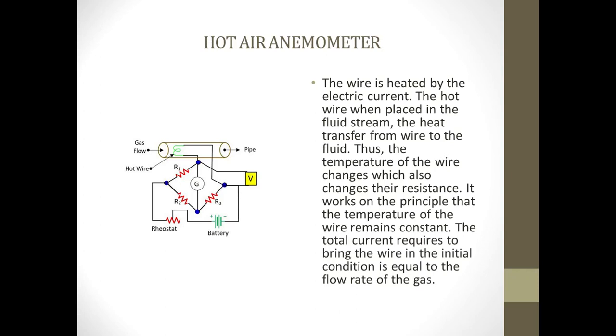The hot wire technique of measuring flow velocities has assumed great significance as the measurement can be done without disturbing the existing conditions. The method can be used for measurement of low velocities. The hot wire probe can be placed in small size pipes without causing any pressure drop in the fluid stream.